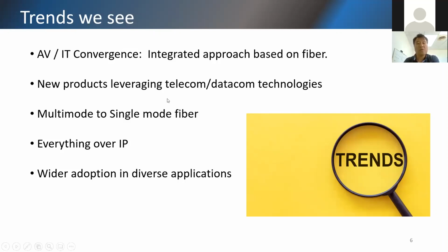A lot of this has to do with borrowing or leveraging technologies from the communication space, such as using more single mode fibers. Way back then, multi-mode fiber was maybe a little cheaper and easier to integrate, but that's not the case anymore. There's far more demand for single mode fibers in the communication space. Prices are cheaper, and there are a lot more interesting solutions available.